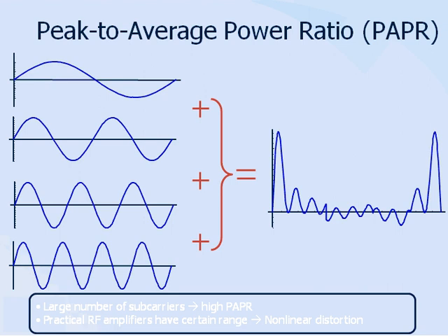And we have some questions. Okay, so someone wants to see the impact. When you have inter-carrier interference, the frequency itself is changing. So instead of having F1 as your subcarrier frequency, let's say instead of 15 kilohertz, it will become 14 kilohertz. So the subcarrier itself will have a different frequency.